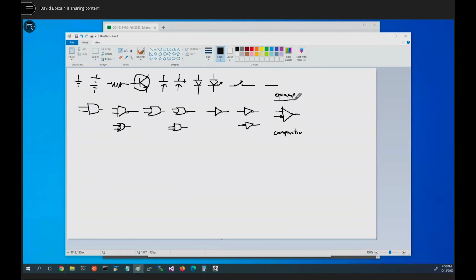So while an operational amplifier is in fact a linear circuit, meaning it's normally not used in digital circuits directly, when it's used as a comparator, it's able to perform a digital function. It will either be all the way high or all the way low. They might ask what happens if they're exactly the same. They never will be. You just can't do that with one of these things. But if you did, if it were even the slightest bit off, it would jump all the way to one or the other of the voltages.